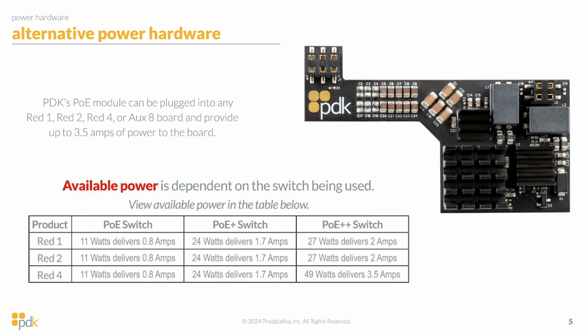So when you plug it into the pins on the board, it is going to siphon as much power as you provide to it. So you have 3 PoE standards that you can use: PoE, PoE Plus, or PoE Plus Plus. And whichever switch you use and whatever you configure that port to utilize is what the board will take in.